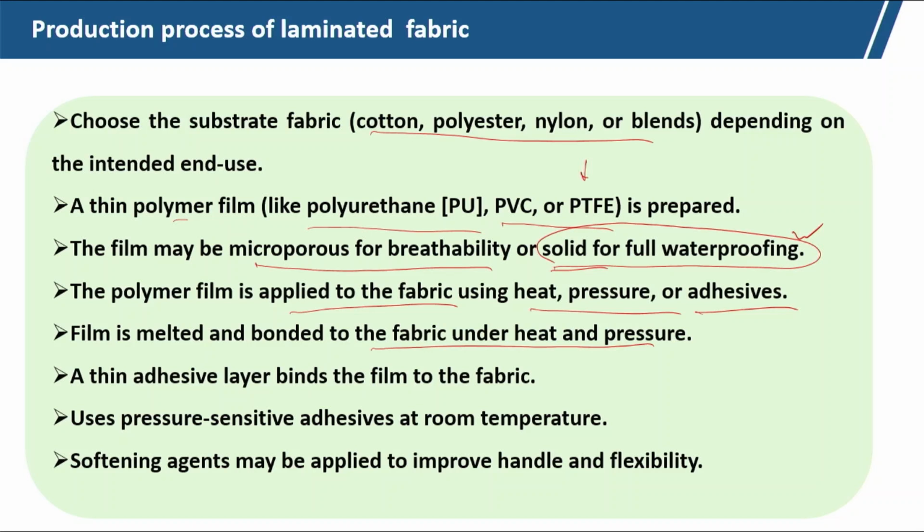Sometimes, if we do not want melting and bonding, adhesive can be used. A thin adhesive layer binds the film to the fabric, using a pressure sensitive adhesive at room temperature. At room temperature, if we apply high pressure, that will give a nice bonding.